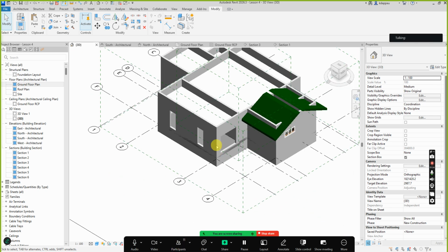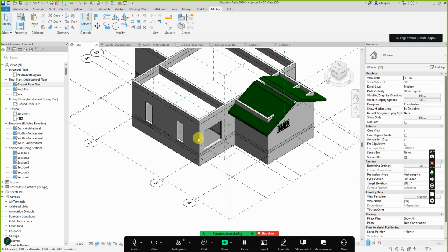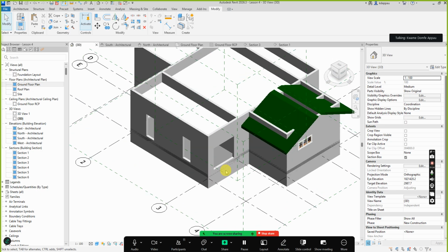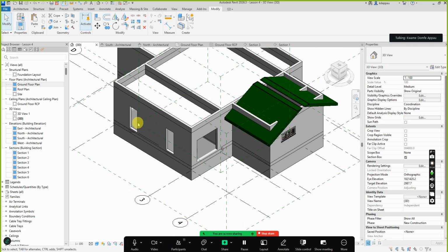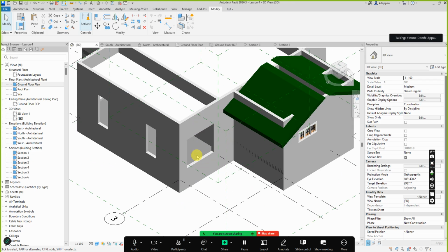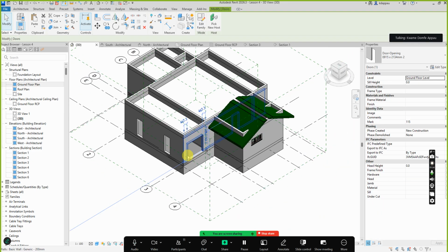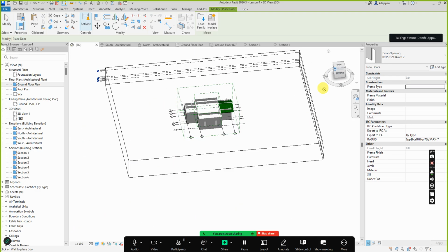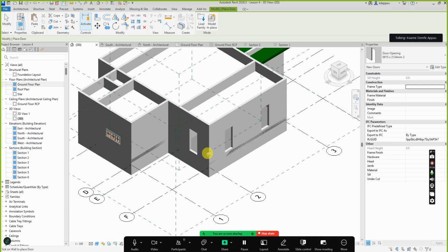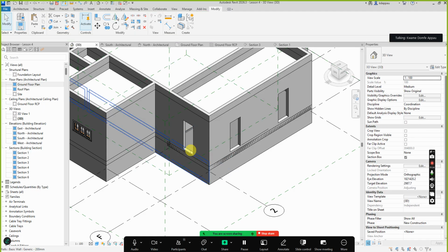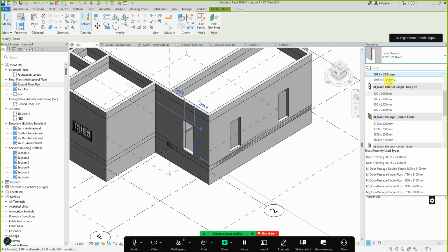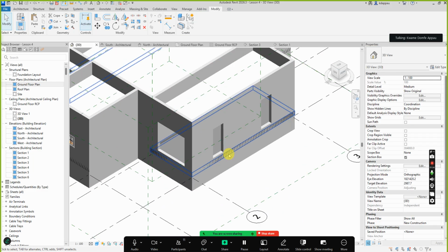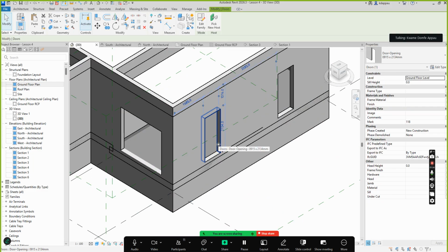Okay. So, when I want to create an opening at the entrance here, I prefer to edit this opening and then create some here. So this opening, I can place a copy here. I can take it, create similar, go to this other side here, and place another copy. But already there's one small one here, so I'll just select it and change it to a bigger one. Let's say this one. The one in front, let me delete this one.